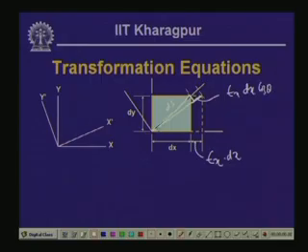Now, this is the angle which has been changed because of this stretching, and let us call this angle as alpha 1, and then alpha 1 can be given as this divided by this distance. Now, this particular length is nothing but the extension which is epsilon x dx times sin theta.